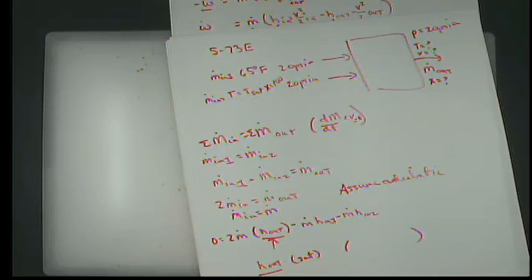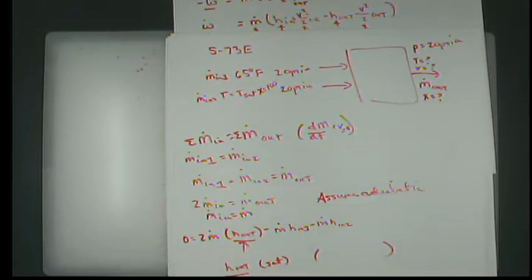What do you think? Yeah. That's still a little iffy, but I understand. Yeah, I'm not really crazy about it either, so I have to tell you, that bothers me, and also just the fact that there's no heat given. I mean, I'm not convinced this would be an adiabatic process either. Because wouldn't it, if it ever tried to get above, like if that was closed off, wouldn't all three of those go up? Well, sure. If you closed it off, this is a really good point. If you closed it off, what would happen is mass would accumulate inside of the mixing chamber. I mean, you could build pressure. The pressure would build up. Exactly.